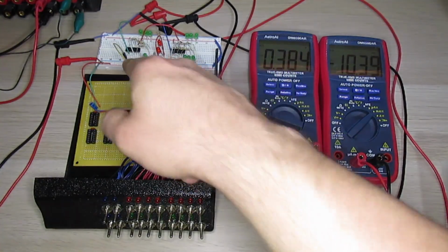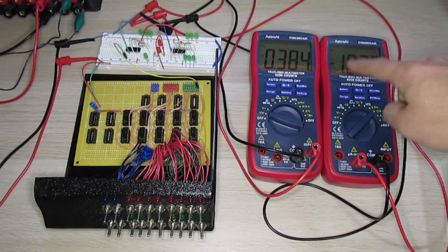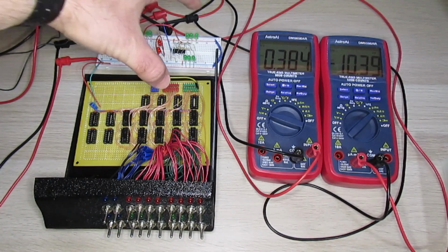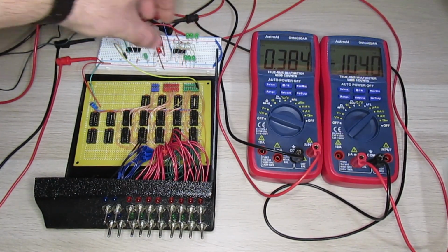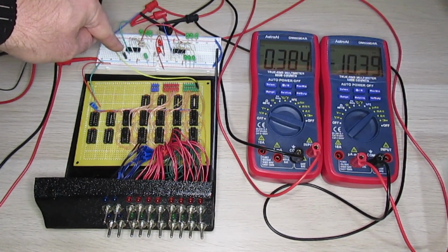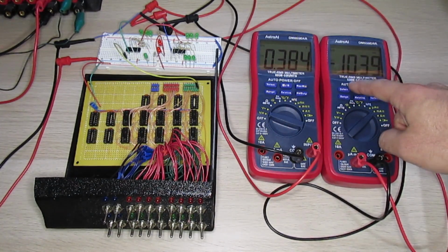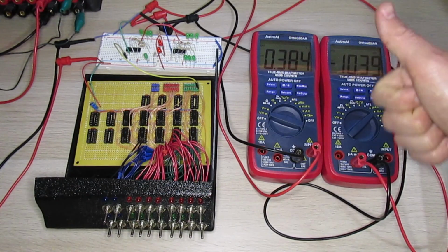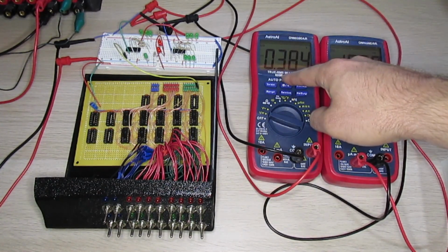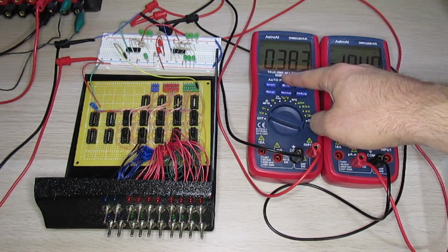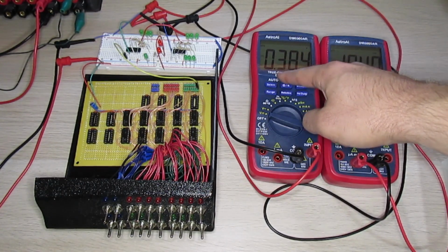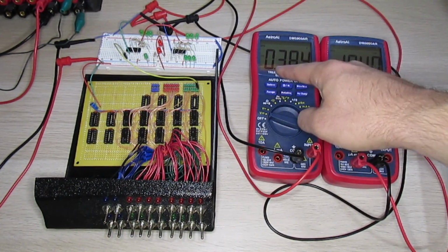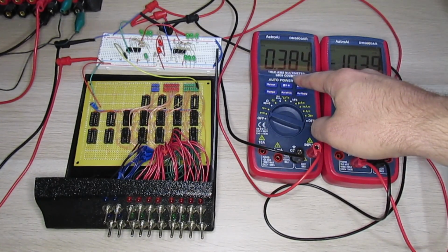So right now the output of that inverter is low. So you can see we have just a bit over 10 milliamps going out of all of the inverter inputs and into the output of that one inverter. And that's still pretty well below the 16 milliamps that the datasheet asks us to stay under, so we're good there. And the output voltage is still within the datasheet range. The datasheet says it will never go above 0.4 volts as an output low voltage. And it's a bit close, but we're still in there.